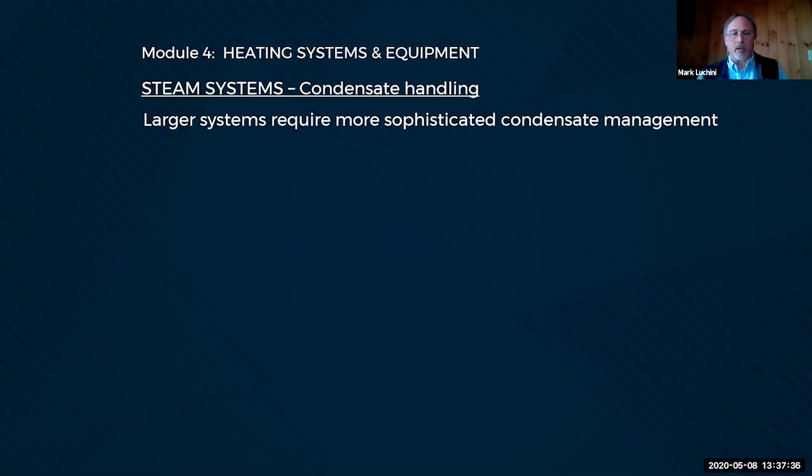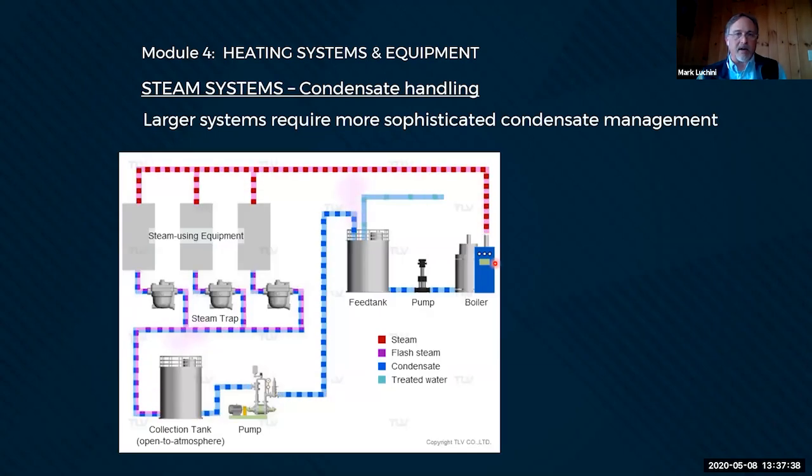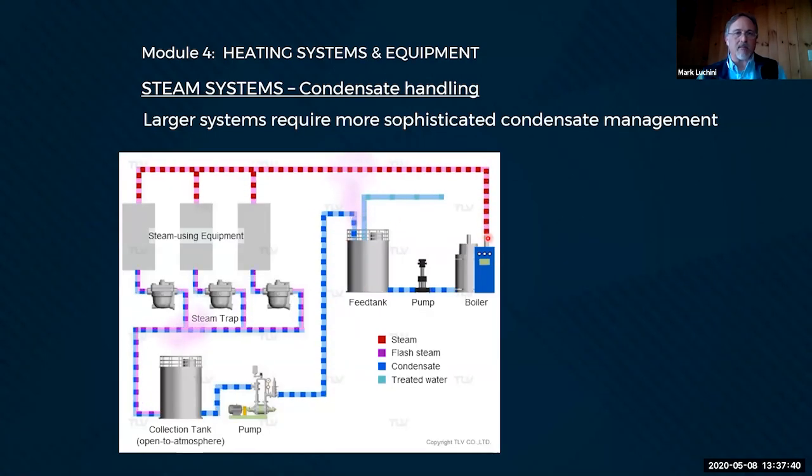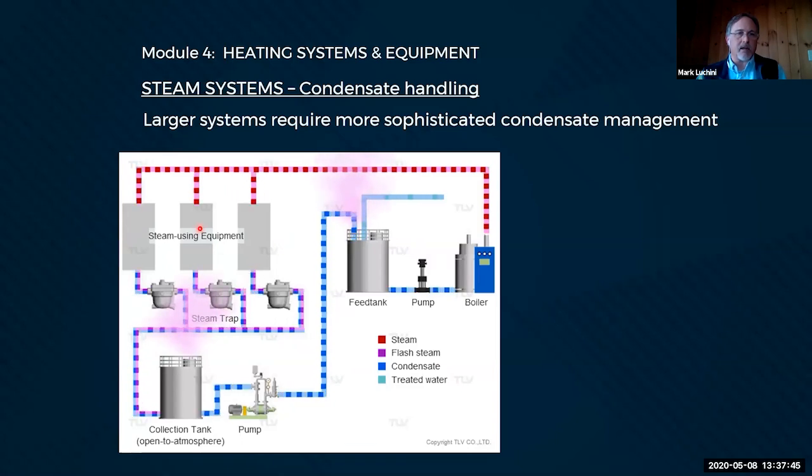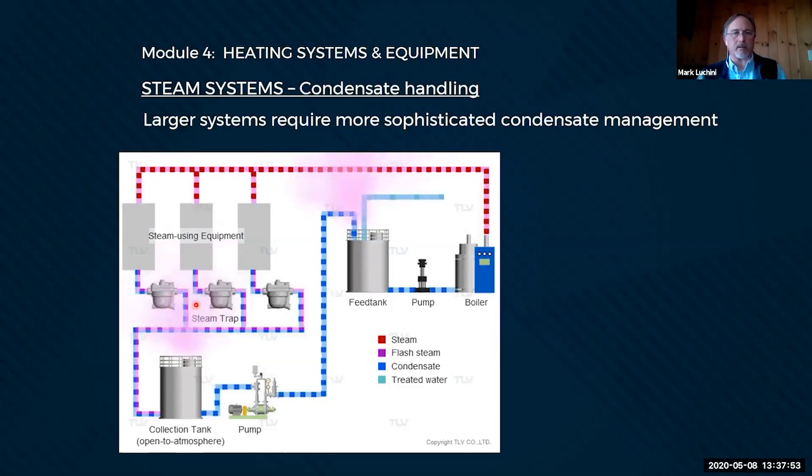So for example, here, if I have a boiler system in the basement level, I've got a bunch of equipment sitting on the basement level, and all the steam flows into my heater coils and comes out through my traps. And now I'm basically at the floor level. I can't pitch back to the boiler, so I have to go down into the sub basement where I get picked up by a condensate receiver and pumped back either to a feed water tank or directly to the boiler.